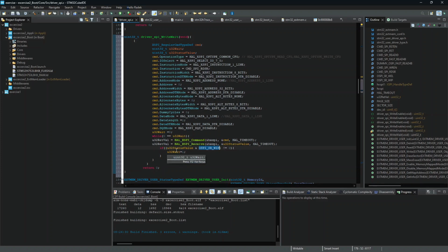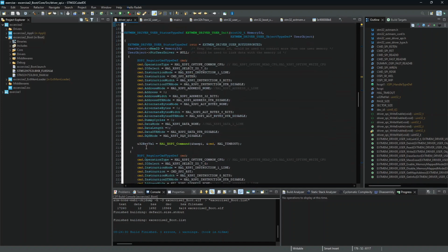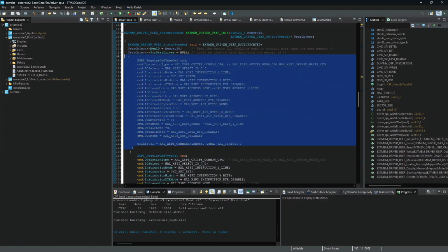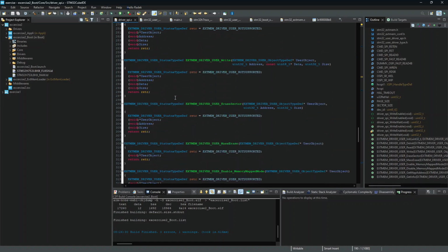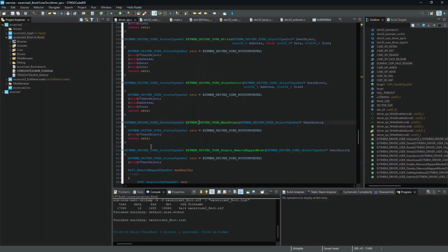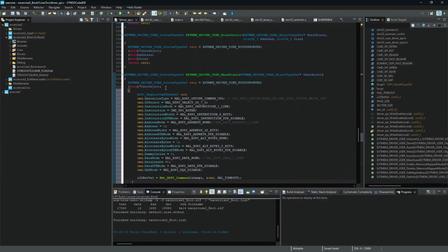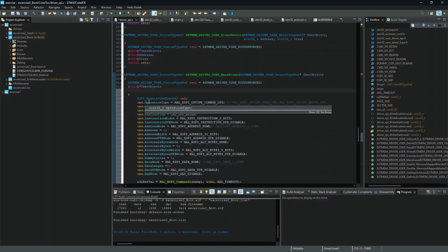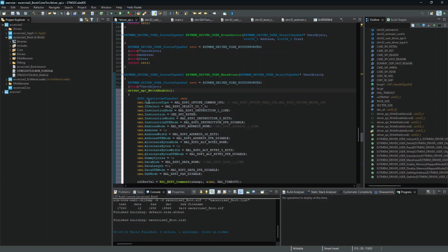And if I now have these support functions, I can finally implement the erase operation or the mass erase operation. So I will again take, for example, the reset enable command, and I will go into the mass erase. I put it here. And first, before I use this command, I will call the driver write enable.